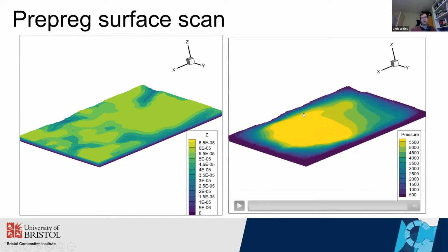So we start getting higher pressures in this region here, where we've got a trapped bubble region there, and the resin in contact with the top surface. And then at the moment, in the simulation at the outer boundaries, we've got the resin chamber pressure. So we've got a drop off in pressure there. So we still need to do a little bit of work on what outer boundary conditions we're going to apply for the pressure equation for the resin in this case.